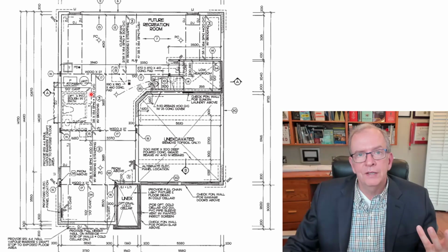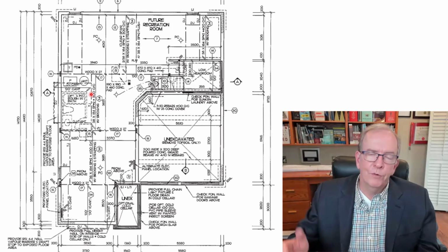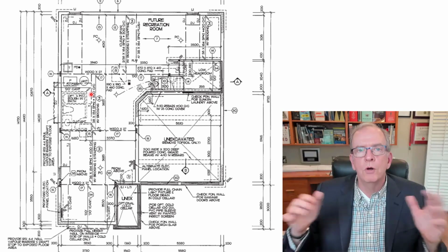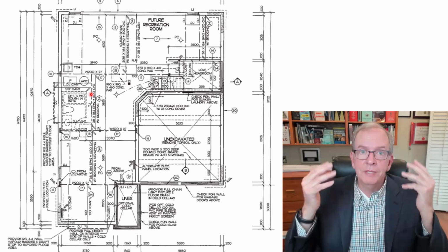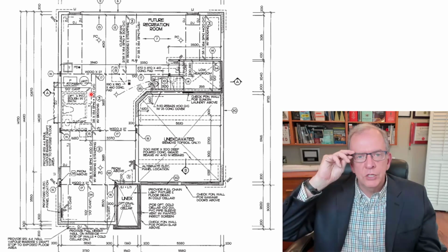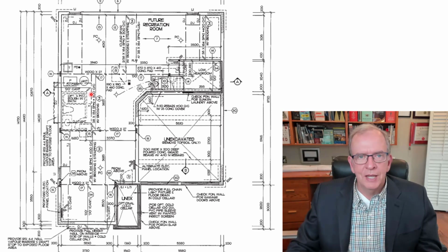But very often, that's fine. It says 300 on center, but when we lay it out, it's 12 inches. If it said 400 on center, when we lay it out, it's 16, because our sheets of plywood, our drywall, everything is imperial, 4 foot by 8 foot. And we ship 10 times that to the US, so that's why we stick with it as far as our material of choice whenever we're doing anything in construction. It's always good, though, to know both methods, even if your jurisdiction uses only imperial. You never know where you're going to be working, where you're going to be traveling, and what changes may take place. So hopefully that gives you a good understanding.